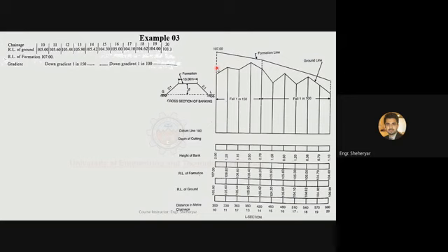at this point? Yes, take the elevations at the point where I want to make filling, and then take the elevations up to where I want to fill. So take the difference between them, then it will give you the height. Yes, the difference between the reduced level of the formation level and the reduced level of the ground level will give you the height of filling or depth of filling.